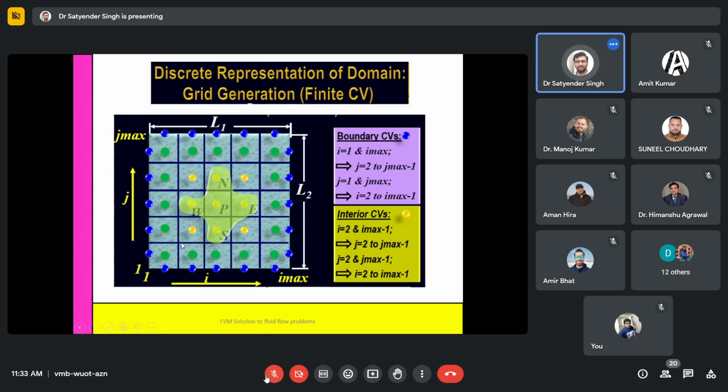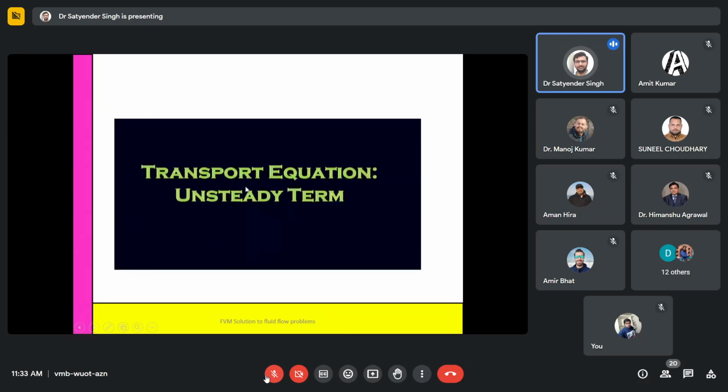Because in a fluid flow problem, fluid will be, let's say, coming from left to right. So you will only assign one velocity, let's say the u velocity, at this boundary, and you will be unknown with the velocity value everywhere in the computational domain, even at the outlet. So there will be no reference to calculate a value at the grid point in a particular direction. So what we do, by considering a weightage function, is assign weightage to the previous neighbor grid and a boundary grid, and we will be augmenting inside. So this approach I am just going to tell you now.